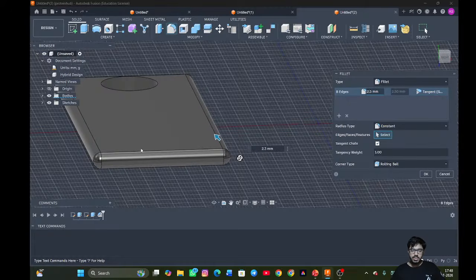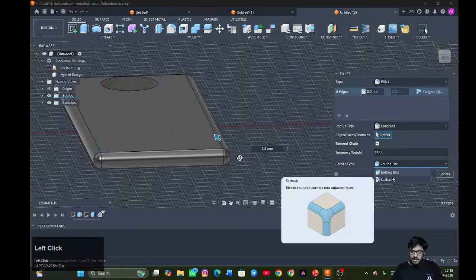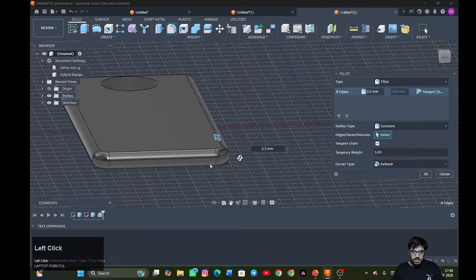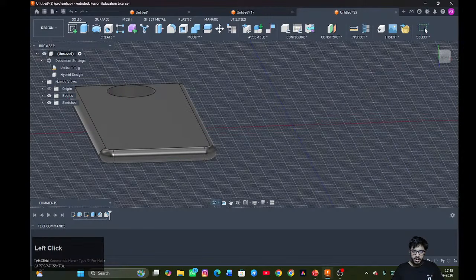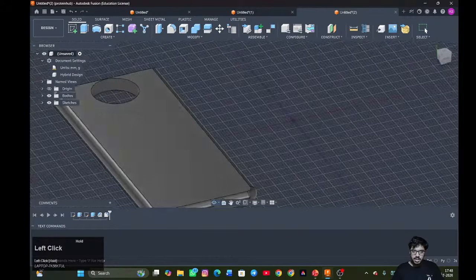See, if we do 2.5 in a 5mm width thing, it becomes a total curve, because 2.5 from up, 2.5 from down, so it merges. So I'll set back more, so I'll do this. Yeah, okay. So this is the keychain.